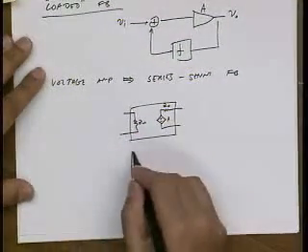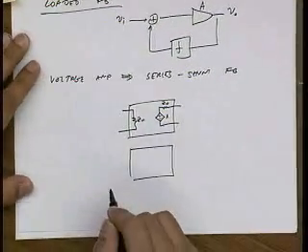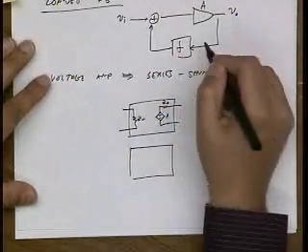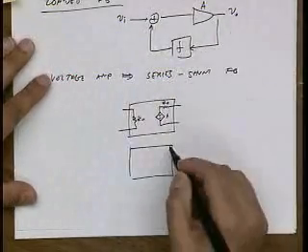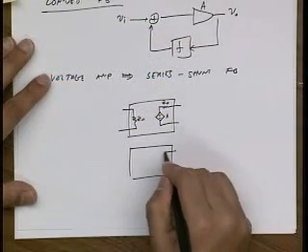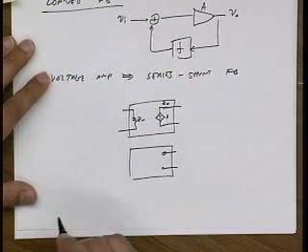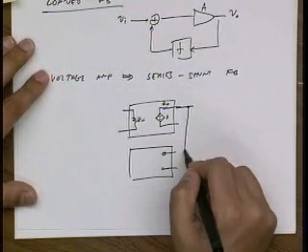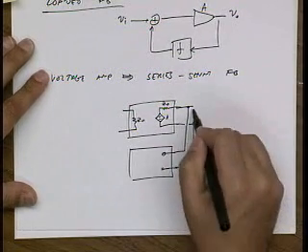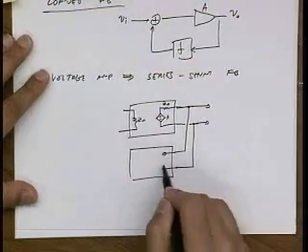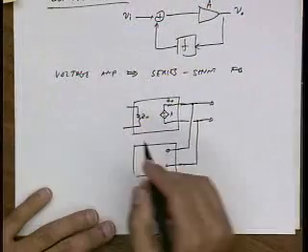And then I hook up my feedback. My feedback is also unilateral, right? This feedback doesn't allow any signals to go forward, so I have to emphasize the fact that, first of all, my feedback does not load my circuit. If I take a connection in shunt, it's an open. It doesn't load my circuit at all.